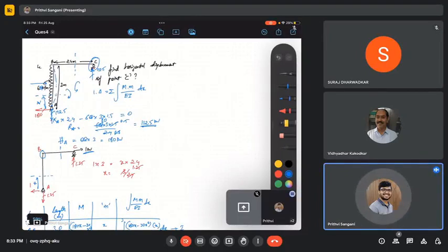See, we made a blunder in this. You can see this, we also have a horizontal reaction in A, right? Yeah, that will actually compensate that. So it's better you take the moment at A as zero initially, and you find out the vertical reaction at C. You're able to understand? Yeah, that we missed out. Initially even I missed out.